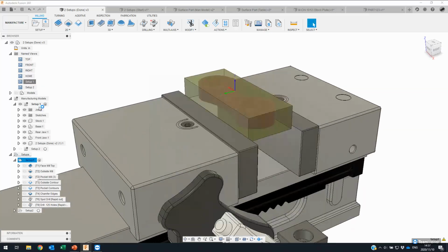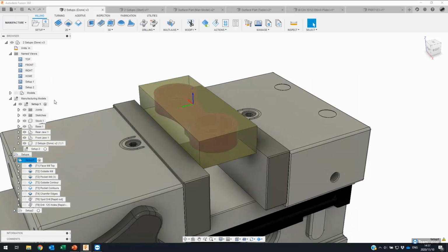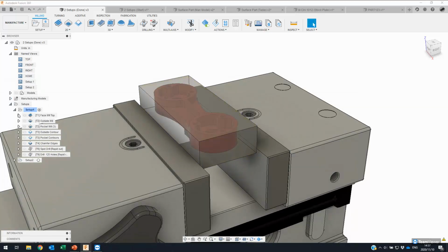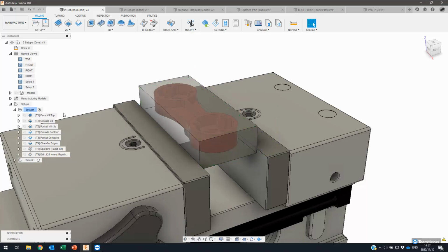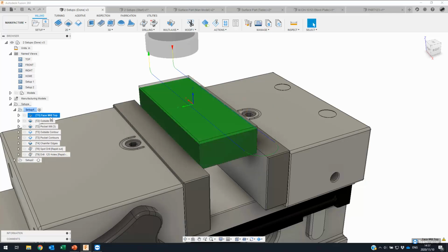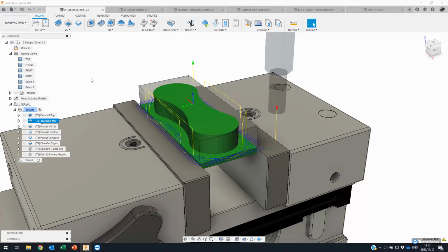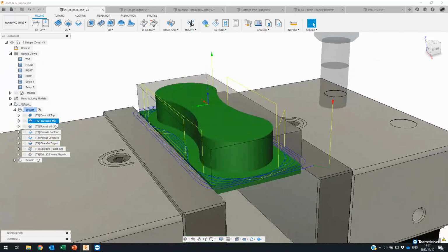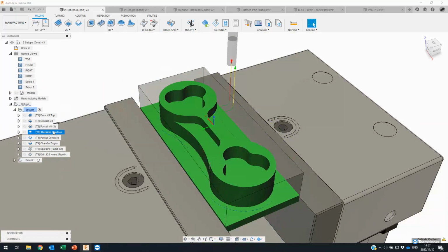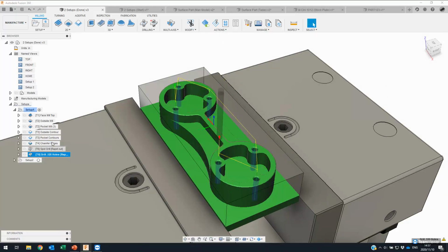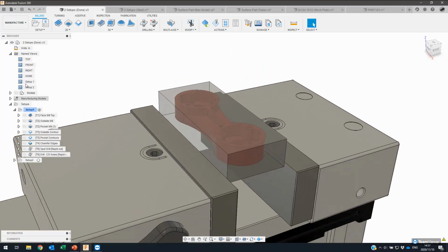And here for the completed setup, go to Setup 1 and view the setup and toolpaths. And while we're here, I'm going to just talk quickly about the simulation improvements, where you're able to either hover over an operation and see its toolpath, or you can select the operation and it will then display the in-process stock simulation. So you can actually see by clicking on the part or on the operation the resulting stock removal. And so here we have our setup 1.